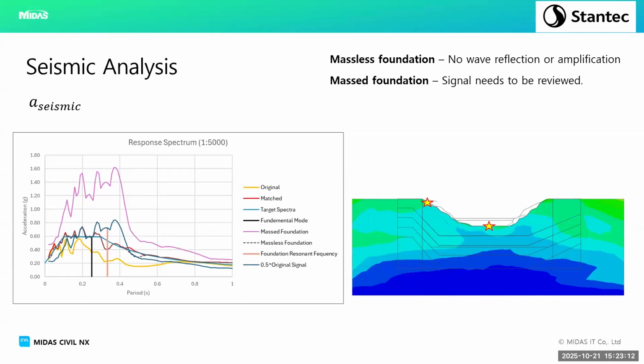And you can see there, I can't read the legends, but essentially you can see that once you descale it, you can bring it back to the spectra. There'll still be an amplification at the natural frequency of the foundation. But in the realm of the foundation, reservoir and dam, that period is within the spectra.